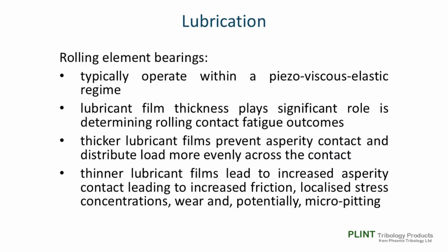Moving on to lubrication, rolling element bearings typically operate within a piezo-viscous elastic regime. It will be apparent that lubricant film thickness plays a significant role in determining rolling contact fatigue outcomes. Thicker lubricant films prevent asperity contact and distribute load more evenly across the contact, minimizing stress concentrations that might otherwise initiate fatigue cracks.